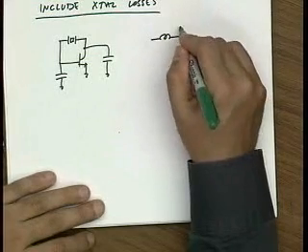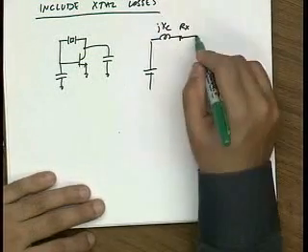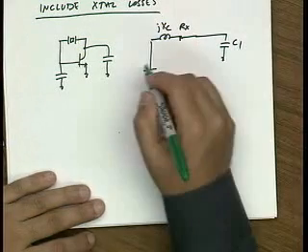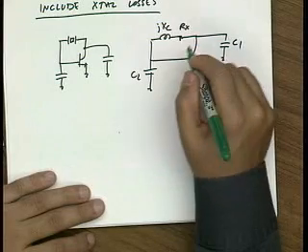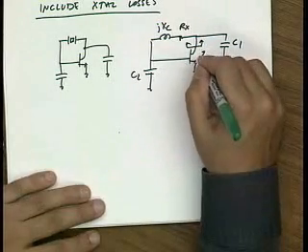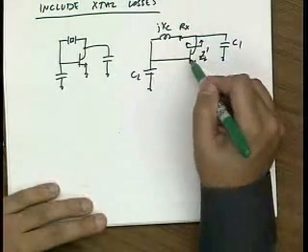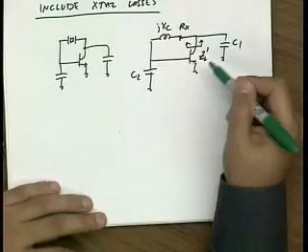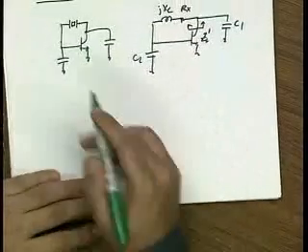The equivalent circuit is Rx with jXc here. Again, C1, C2, this is our transistor. And what we'd like to calculate is the effective impedance ZL prime. Because I need to find my loop gain, so I need to multiply gm by ZL prime to design my crystal oscillator.